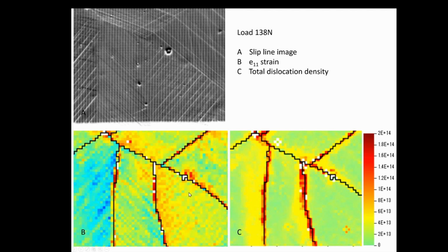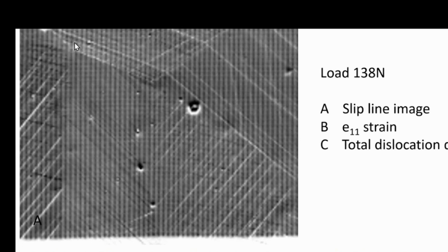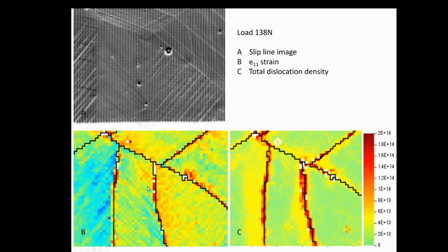But you see, let me just point out a detail there. That's high strain. It's near this, it looks like an inclusion in here. So it might be caused by that. To start with in the talks, I'll be talking about the diffraction patterns that you get from each of the points. And by the way, the dots in the image people will recognize in scanning electron microscopy as being contamination marks where the beam rested while we collected the electron backscatter diffraction pattern. So you just get an idea of how many patterns were recorded just to get this image down here.